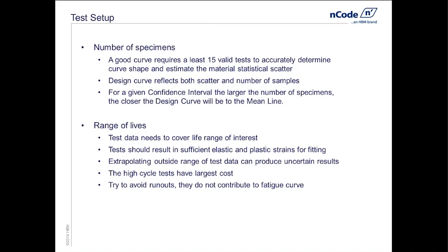The thing we never want to do with these curves, since we're fitting this curve through test data, is extrapolate. Extrapolation is very unpredictable. The curve has been defined by the test data, and areas outside the test region basically have no control. And so we want to ensure that we're never extrapolating from that curve. We'll see that in just a second.